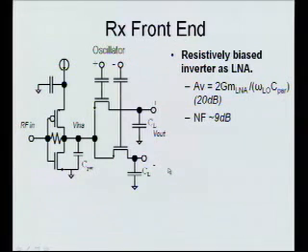Okay, so the noise figure is not great, but this includes that lack of image rejection. So it's really like a 6 dB noise figure for the structure. It's actually not that hard to get a 6 dB noise figure. And the bias current through this is about 200 microamps. So not a whole lot.